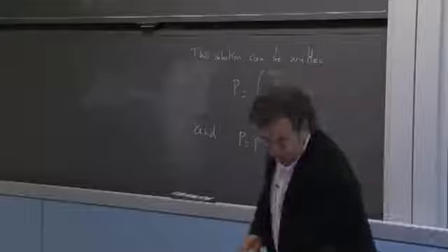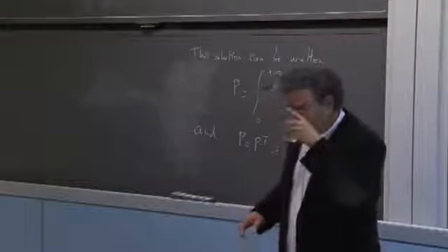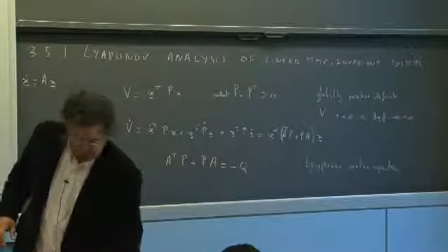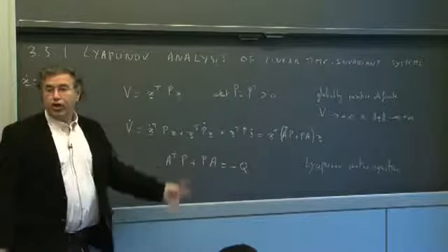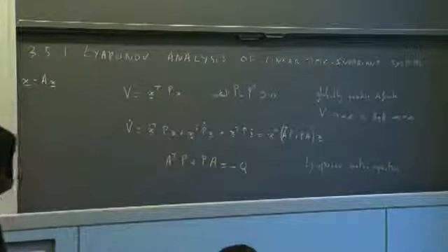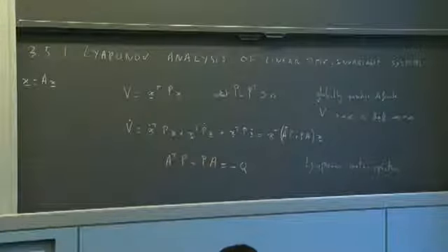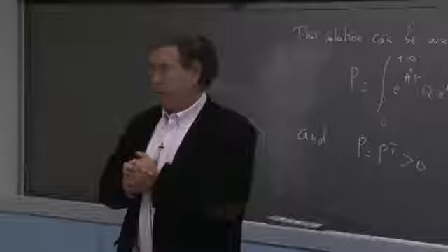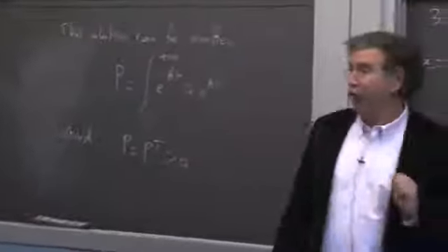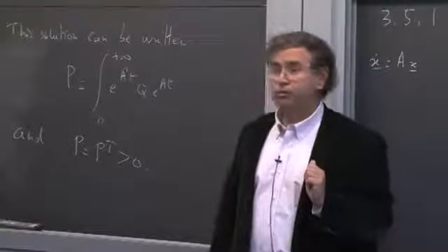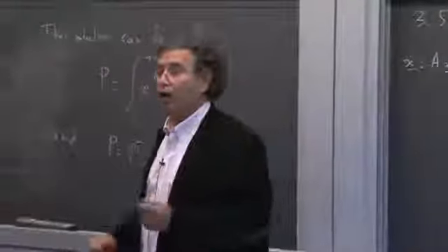All right. So basically that gives you a completely systematic way to take a linear, strictly stable system and come up with a Lyapunov function for it. And a Lyapunov function in the strict Lyapunov sense, with no need of the invariant set theorem, in the strict Lyapunov sense of global asymptotic stability. Okay? Questions?